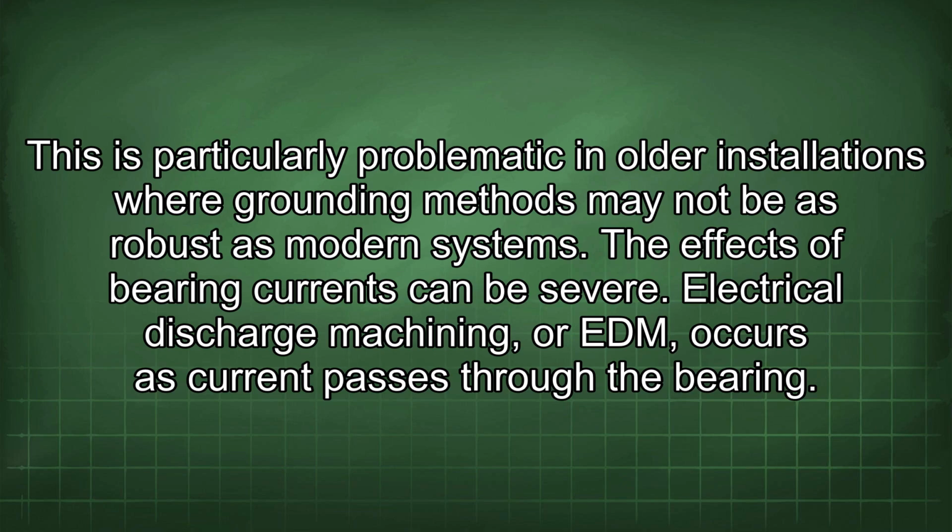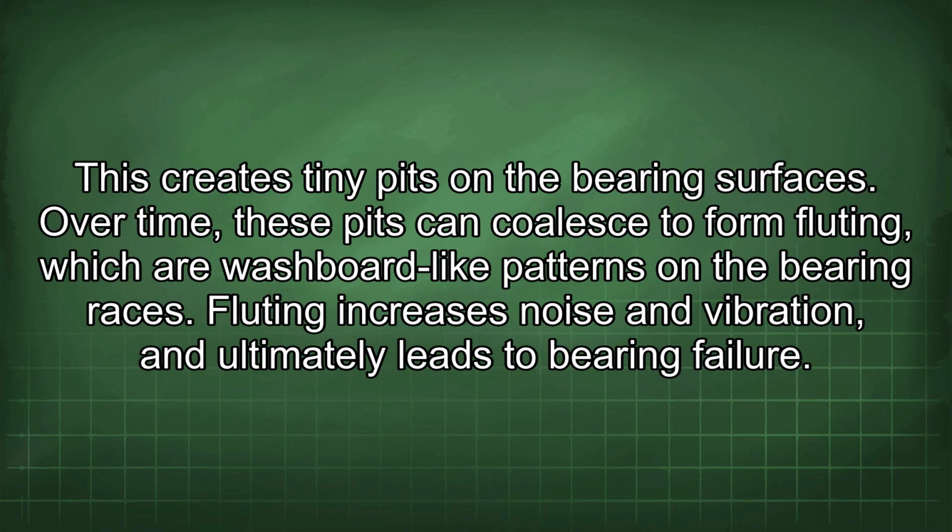The effects of bearing currents can be severe. Electrical discharge machining, or EDM, occurs as current passes through the bearing. This creates tiny pits on the bearing surfaces. Over time, these pits can coalesce to form fluting, which are washboard-like patterns on the bearing races. Fluting increases noise and vibration and ultimately leads to bearing failure.